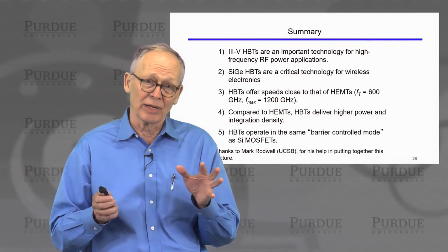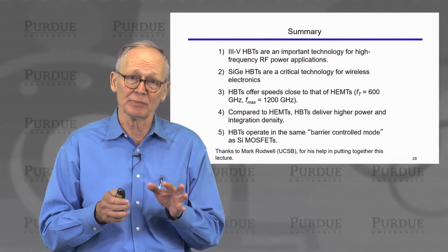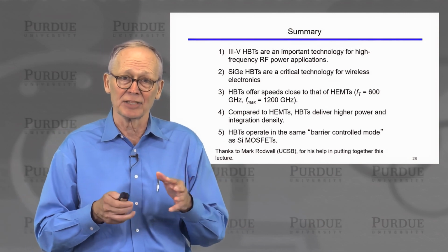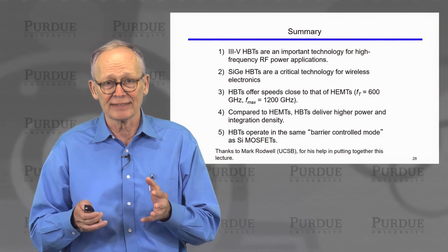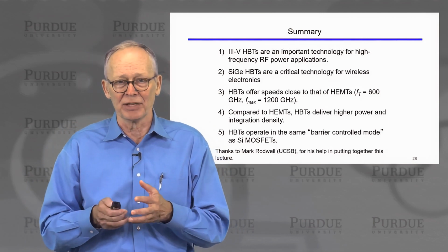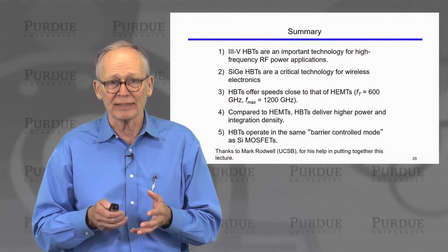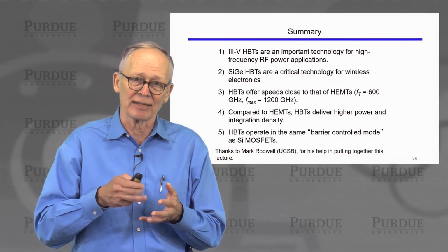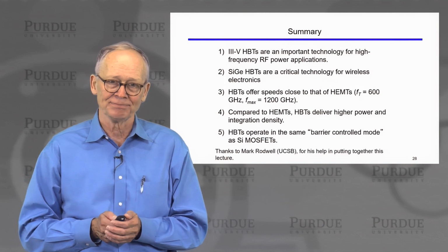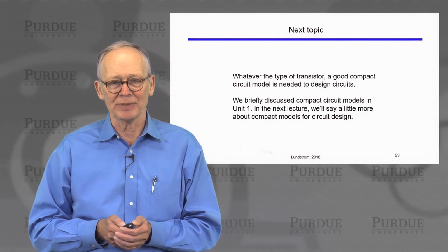But the takeaway line here is that the HBT is not a fundamentally different device than the silicon MOSFET that we've learned to understand. It is a barrier-controlled device. We are just accessing the barrier and modulating it directly with our base-emitter voltage rather than indirectly through a metal oxide semiconductor structure. So that's a quick look at HBTs.